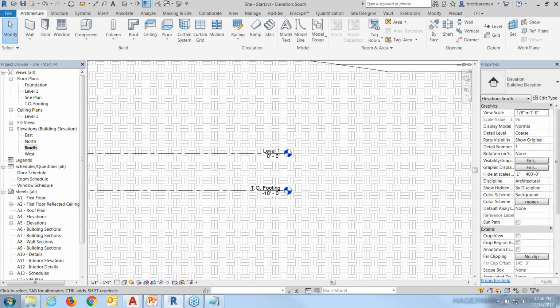And one thing you can do in your CAD file, if you want to, say, create a grid or a rectangle, just use lines and rope off what you're going to extract, then that helps with the realigning center to center in Revit. But in all the examples, everything was centered around Revit's internal origin, or that survey point. So when I brought both data sets in, since I didn't adjust that point location at all, they centered around the same spot, which means that they were where they were supposed to be.